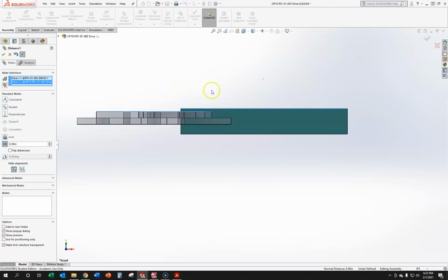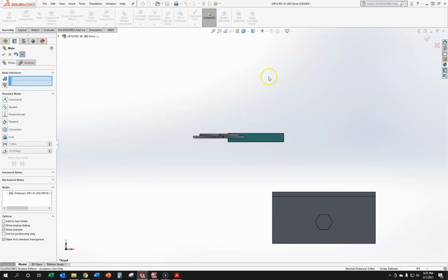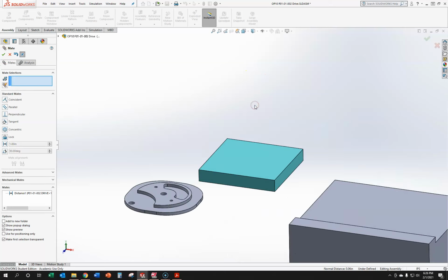And actually 60 thousandths might be too much for this distance, so it might be just do 0.03, so 30 thousandths. That gives us more material on the bottom to work hold with. So I like that. That's good. I'm going to click OK. And now I'm going to go ahead and rotate over and establish my side end pieces here.